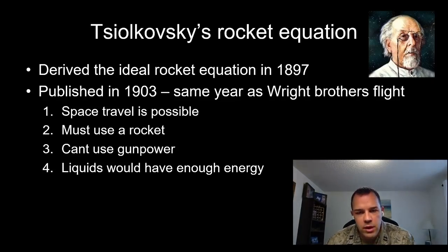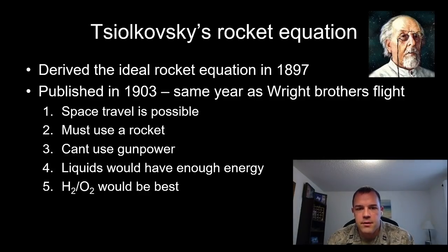He said that liquids would have enough energy, and liquid hydrogen and liquid oxygen would be the best. And in fact, that is correct. Except that you can actually get a little bit more bang for your buck out of liquid fluorine. It's a little bit better oxidizer. And you could also have put little particles of either aluminum or beryllium, one of those extremely reactive metals, in your hydrogen to give you a little bit more bang for your buck. But otherwise, he was spot on that hydrogen oxygen would be the best in terms of fuel efficiency.